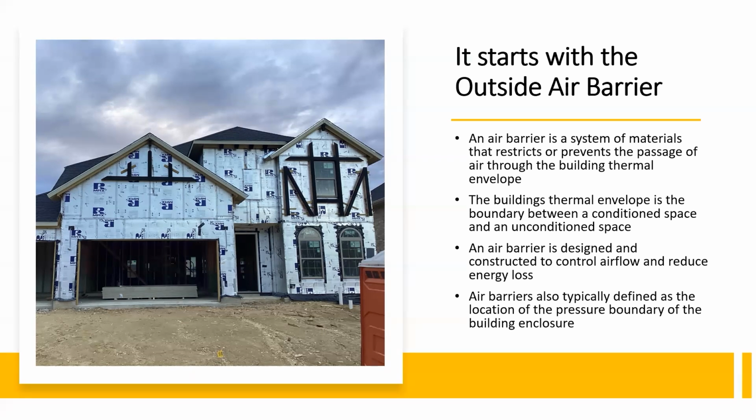It's important to note, though, in multifamily townhomes and apartment construction, the air barrier also separates the conditioned air from any adjacent units. So it's also the fire barrier, the smoke barrier in multifamily townhomes and apartments. The reason I bring that up is, if you were with us last week, it is addressed in the 24, and it states that each unit of these multifamily, townhomes and apartments needs to have its own air barrier. It needs to be able to have its own contained air conditioning without bleeding into the units adjacent.